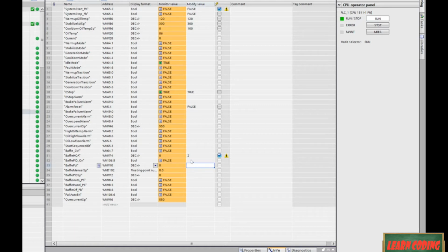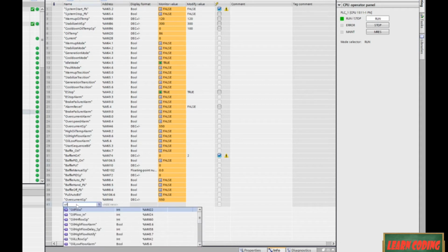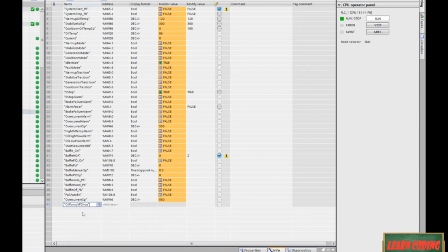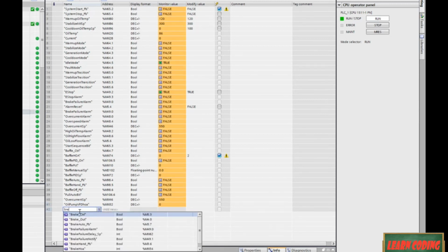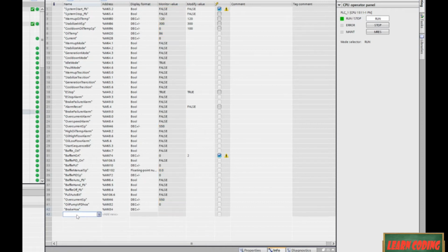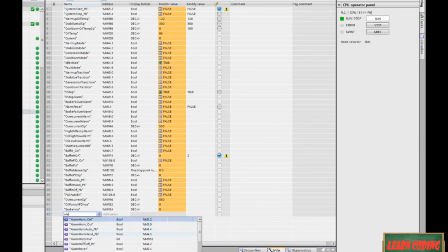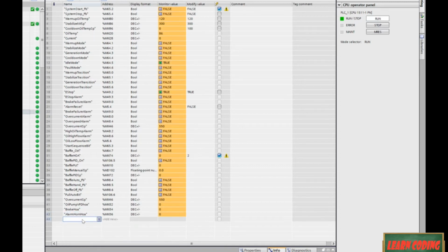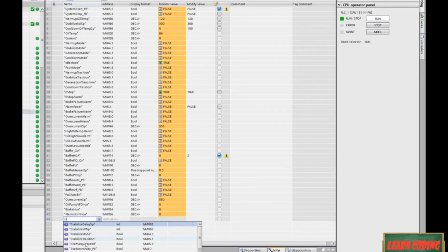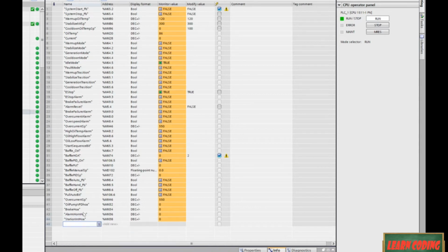We've got, not our control, sorry, our baffle HOA. And we want our oil pump VFD HOA. We want our brake HOA. We want our alarm horn HOA. We want our station interlock HOA, which has got to be around here somewhere. There we go. And I think that's all of our HOAs. So we want to write in 2 on all of those instead of using push buttons. It's just that much faster.